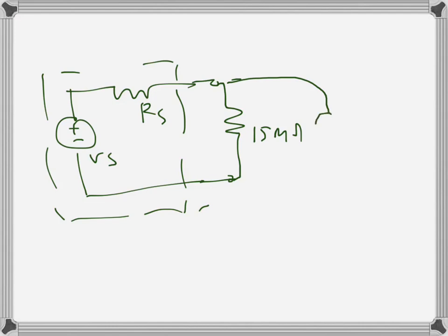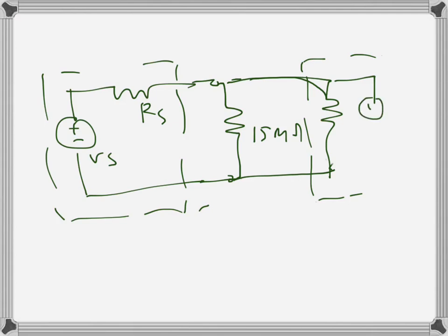The voltmeter also has an internal resistance. Sometimes it's drawn as a parallel, but the basic thing is this allows a path of 10 mega ohms, its internal resistance. So the drawing is better like that.